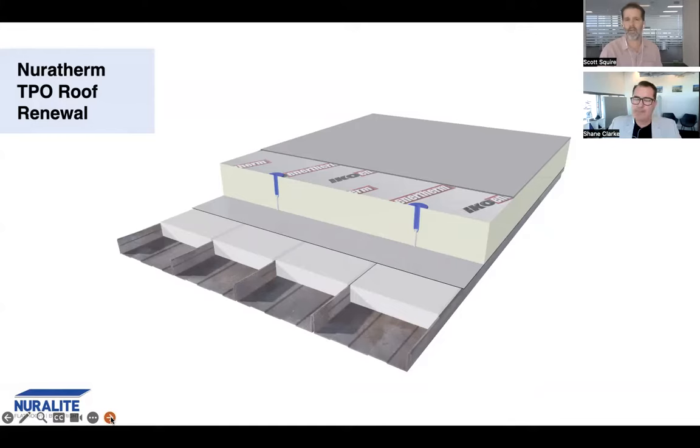You can actually overlay it twice in its lifetime. So after 30 years, you just put down another layer of cap sheet that then commands another 20-year performance warranty. And then at 60 years, you do another layer of cap sheet again. That's thinking about durability, not having to deconstruct is definitely worth factoring whole of life in.